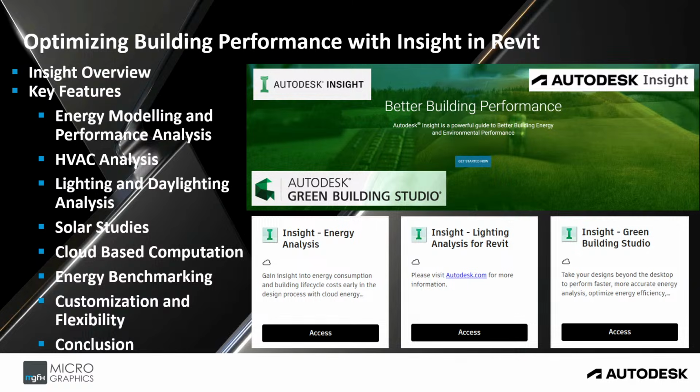The energy modeling and performance analysis. Insight uses a robust energy modeling engine to create detailed simulations of a building's energy consumption. With these tools, architects can assess a project's potential energy use intensity, the EUI, based on various design parameters like orientation, insulation levels, and occupancy patterns. The energy model takes into account external conditions, such as climate data, to provide accurate insight on how the building's location and orientation will impact heating and cooling needs. This allows for optimization of the building's envelope and structural components to reduce energy demand.